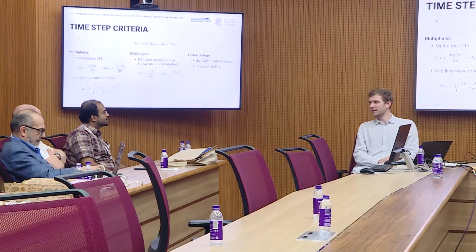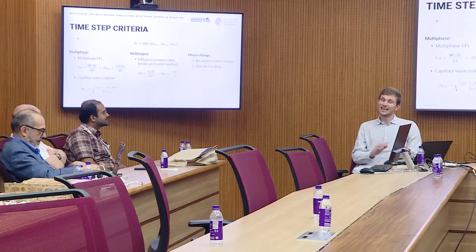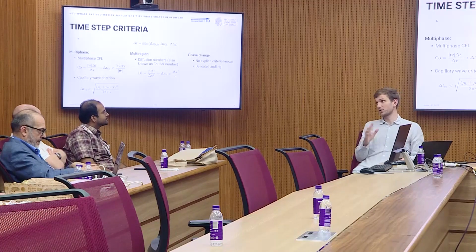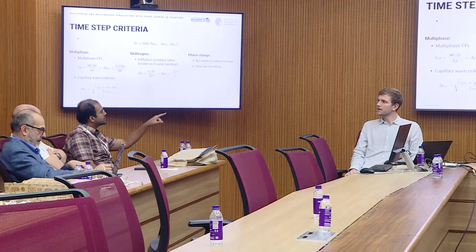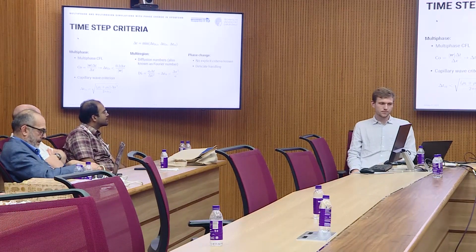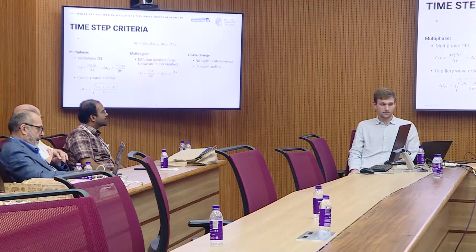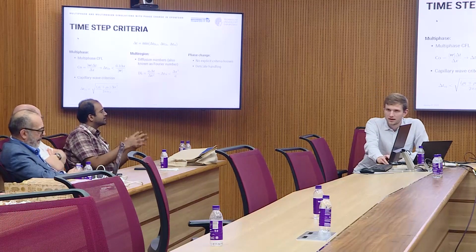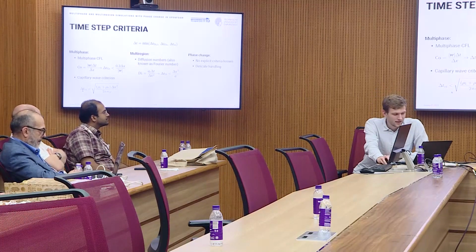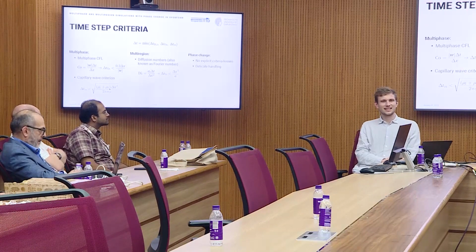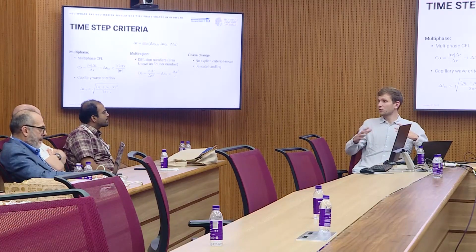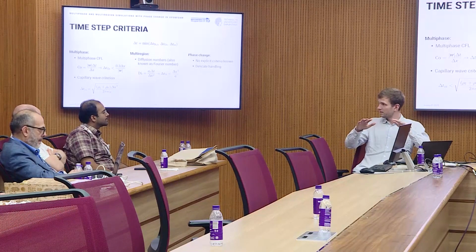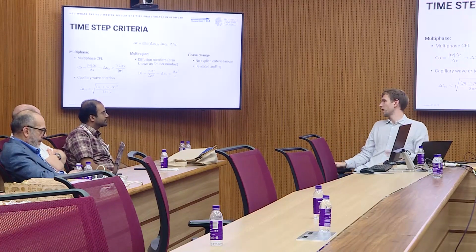Maybe because of the phase change and the surface tension model. Because you also use the capillary wave criterion. Is that the more correct way of using it for just a bubble deformation? Yeah, this criterion is also interesting. In my experience, it is not so much a stability criterion, but I understand it as: do you want to see the capillary waves or not? It's a physical time step.